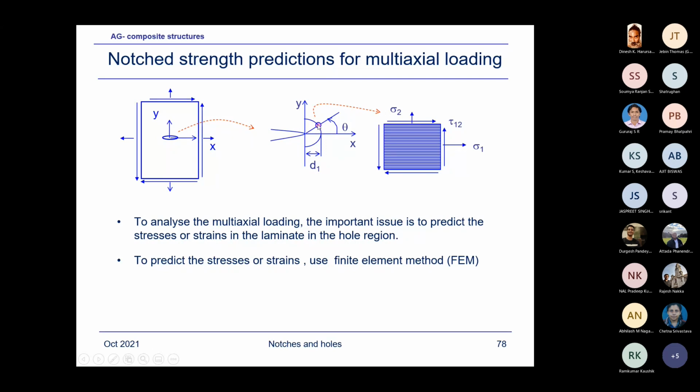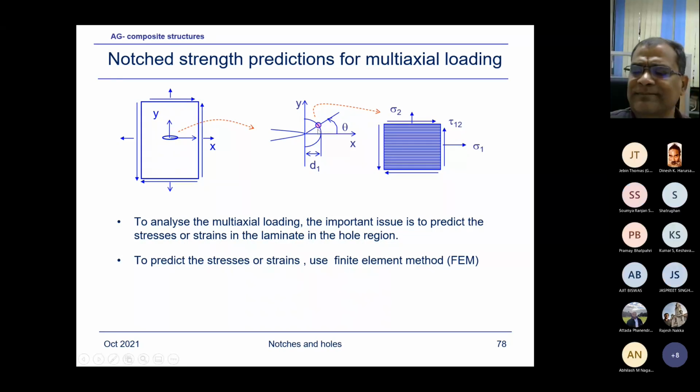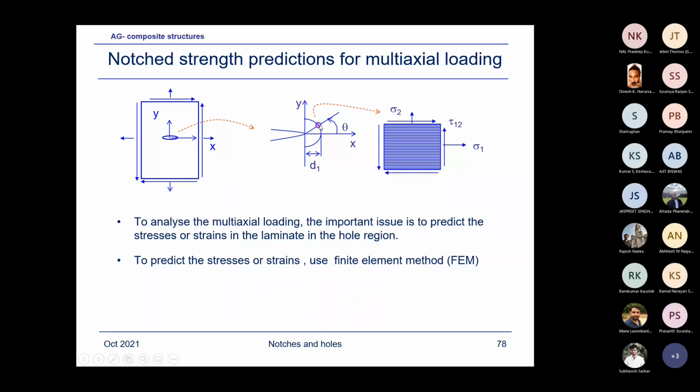You have to use the correct dimension. So use the same procedure. You have determined the correct dimension, and you go around the crack tip along this, because high stresses could occur anywhere. So at various intervals, maybe a 5 degree interval, or 2.5 degrees, you determine at the correct dimension the stress or stresses, and compare with the allowables to determine the margin.